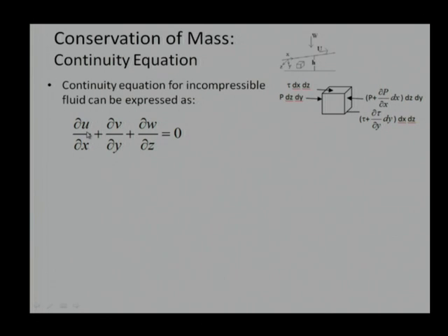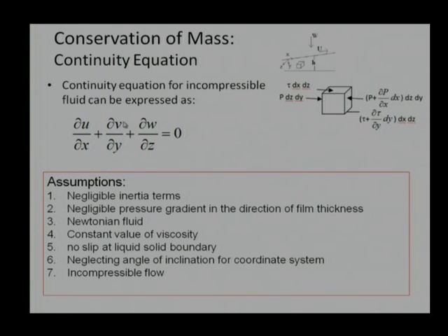In the previous slide, we figured out the expression for u in terms of pressure, as well as w in terms of pressure. We can substitute these expressions, and then find the other equation, or merge the momentum equation into this continuity equation, right. However, we have made one assumption over here, that is the incompressible fluid. That is why we want to add this.